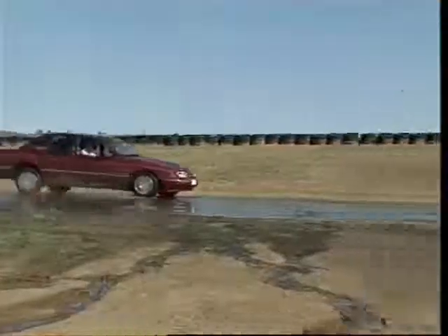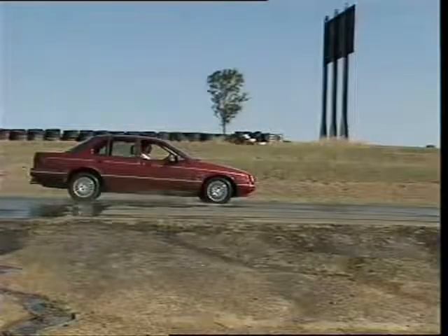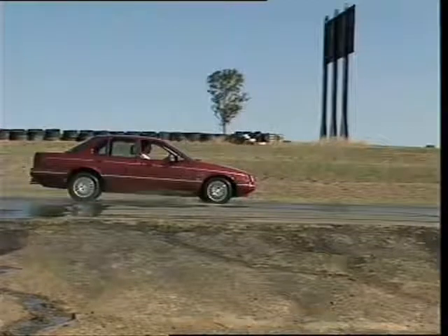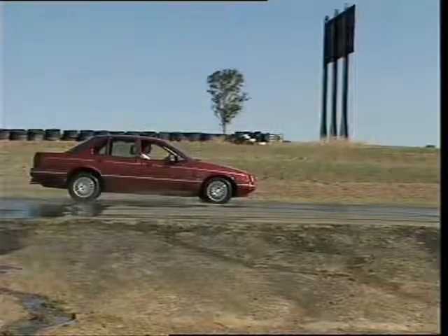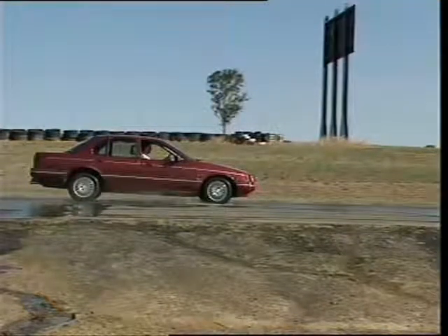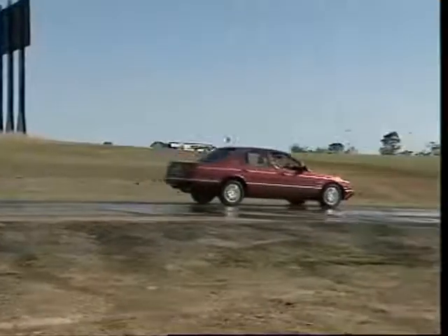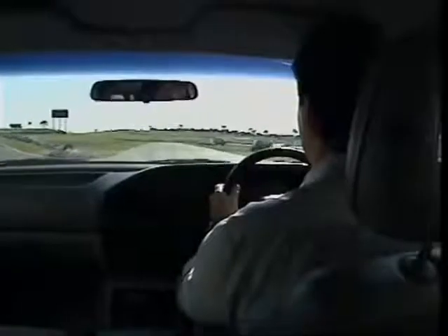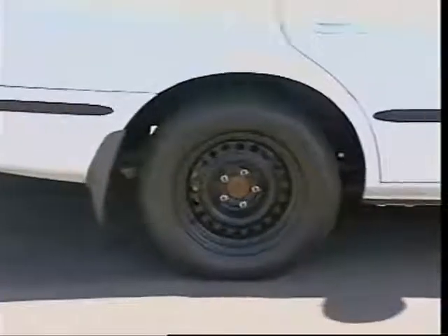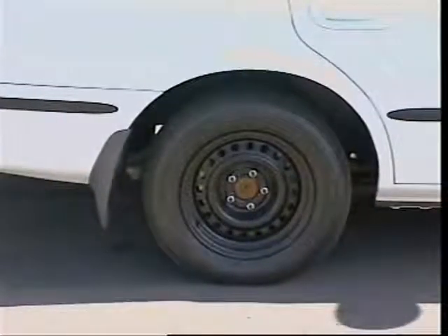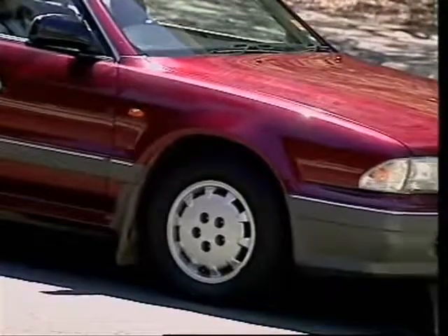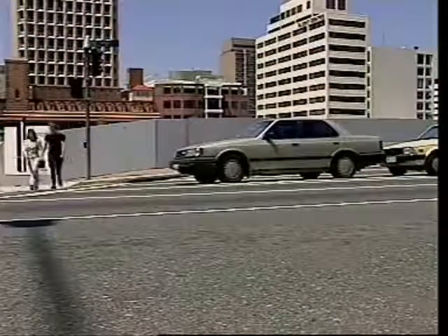Applying the brakes causes the front of this vehicle to dip. This causes greater tyre-to-road friction on the front tyres and less on the rear. This kind of change of load is called load transfer. So if equal braking force is applied to the front and rear wheels, the smaller rear load can make the rear wheels lock and perhaps skid. The braking force applied to the wheels needs to be adjusted to allow for changes in load.